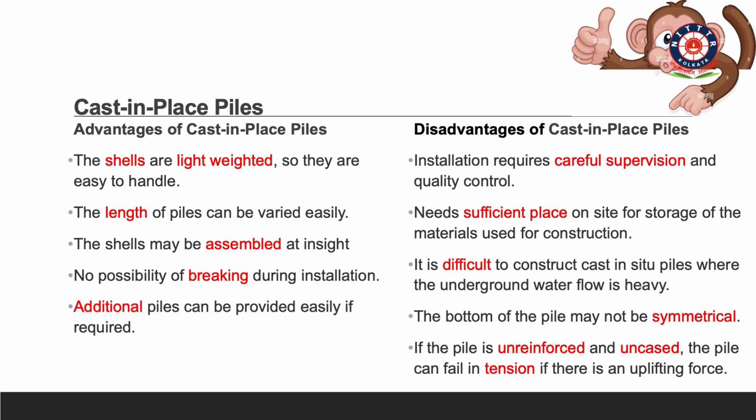And in case you find the pile is not able to take sufficient load, then immediately you can take a decision and increase the number of piles also. So that is the beauty of the bored cast in situ pile. And coming to the disadvantages, installation requires careful supervision and quality control, and also needs sufficient place on the site for storage of the material used for construction.